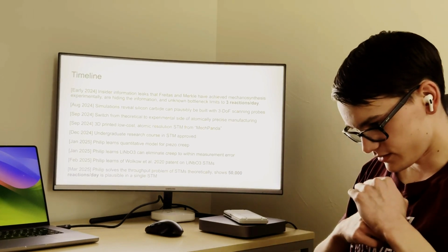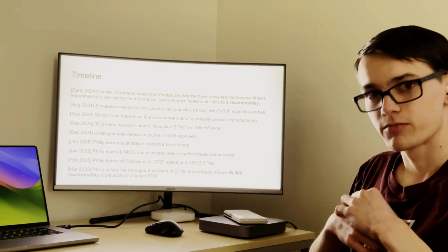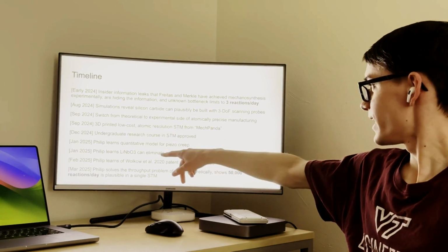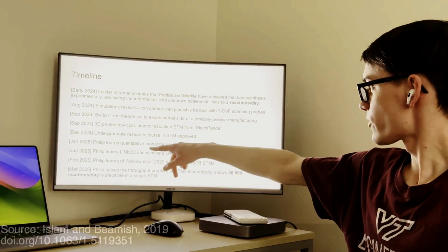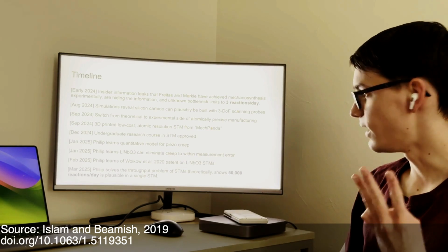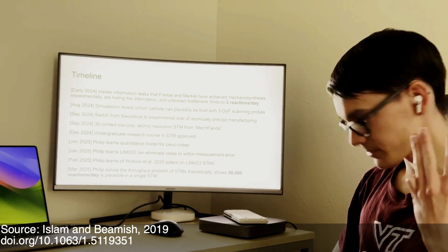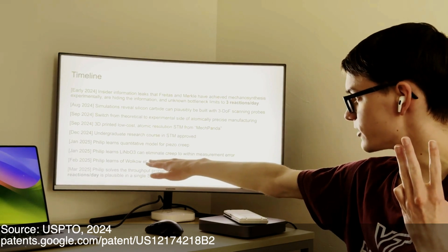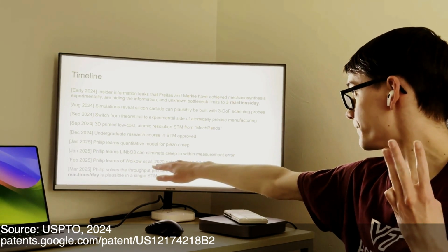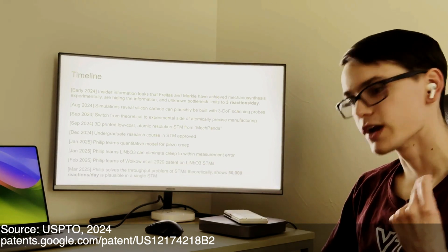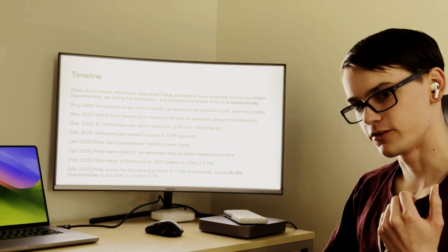I actually learned that the quantitative model for piezo creep is the natural logarithm function. What I found next was another very thorough paper analyzing different materials, and I found lithium niobate was a very promising material. As was explained in the patent by this wonderful researcher who also does stuff that's open source, it can actually cut away a lot of the complexity and all the crazy solutions that were used to try to solve piezo creep.